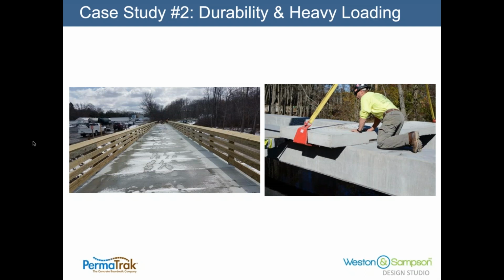The requirement was that they wanted to be able to run an ambulance over the top of the boardwalk. In this case, it was a 30,000-pound vehicle that was provided to the designer, us, on this particular example. So a lot of the components had to be custom sized because of the heavy loading. Again, could they have designed this out of timber? Probably, but it certainly wouldn't have had the durability. It would have been difficult to design a boardwalk with that type of material for such a heavy design loading.